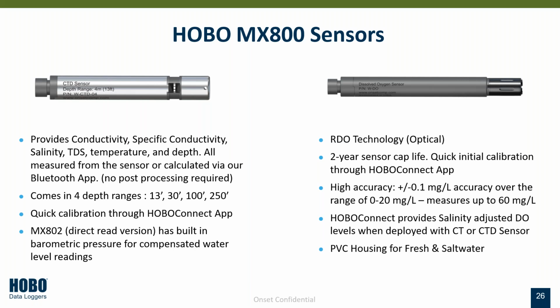The CTD sensor, you're going to typically do a calibration process at the beginning of each deployment. That's done right through the app. You'll buy a calibration solution, or you have your own calibration solution. You'll drop it in your beaker with that solution in it. The app pulls it up. It'll tell you if it passes or what it's reading, and calibrates it right there. You're on your way. It takes probably 30 seconds. And you do that before your deployments or every time you offload and clean your sensor.